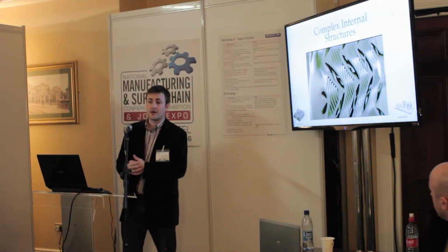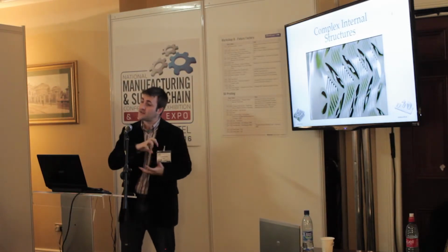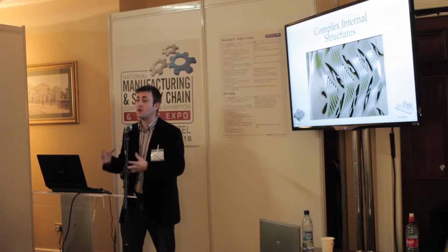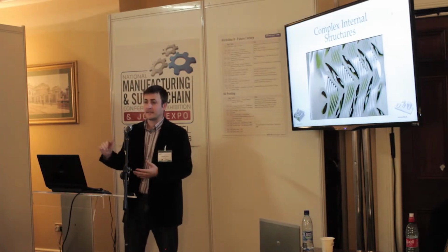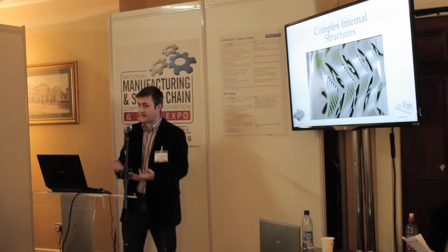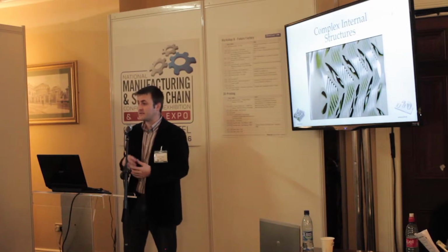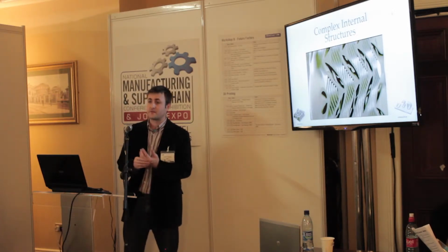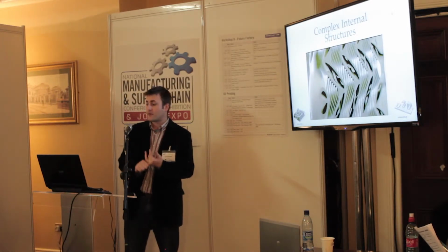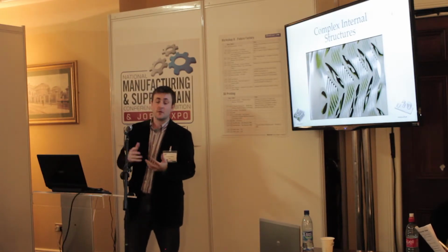radiator that they developed for a car, and you can see that it has very complex designs and a complex internal structure. So that's not possible with standard manufacturing techniques. CNC machines can't machine inside the components. 3D printing can. And in this design it uses heat turbulators. So these basically mix the water as it flows through it. It generated much more efficient heat transfer, and it was a much improved design.